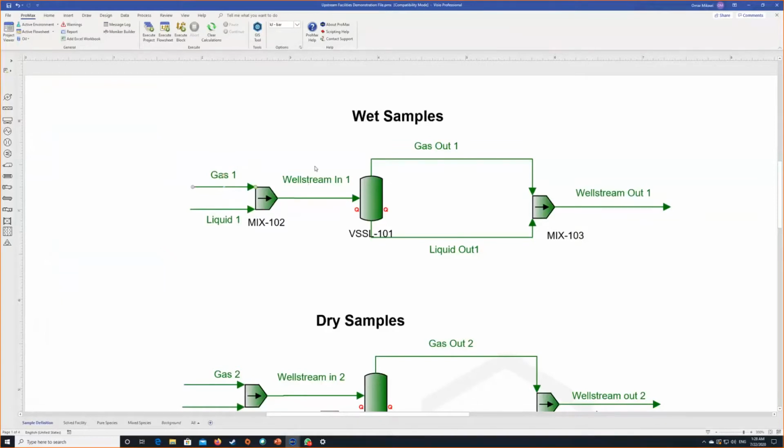According to the GOR. So it's basically what piece of information do I trust more from my lab? Do I trust my composition analysis when I know that labs can sometimes overestimate or underestimate certain components, or not even measure certain components? Or do I trust the volumetric or the flow measurements? I am more trusting of the flow measurements, so I'm going to set this up in such a way to iterate the gas and the liquids such that they can recombine at the accurate GOR.